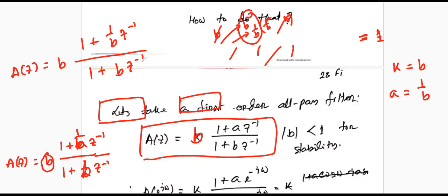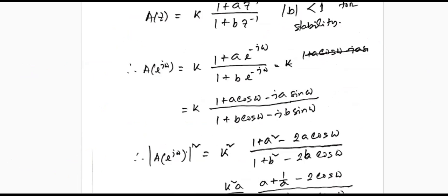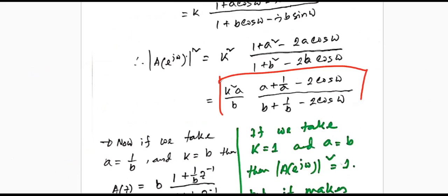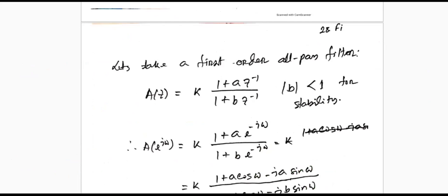And now what we observed here is that we have both the magnitude part and also the phase part, because z is equals to e to the power j omega, so we have that part as well. So we have the phase part in this equation. Try to understand that this equation only gives us the feeling that we have the magnitude 1. And this is the actual filter.